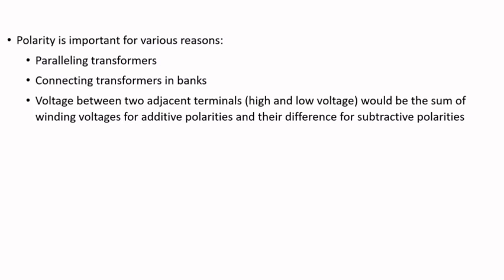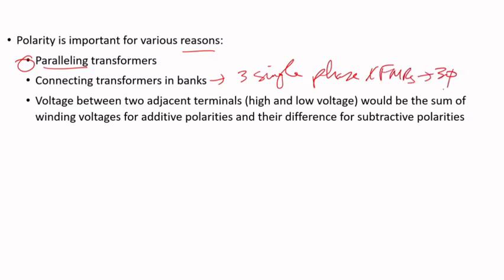So polarity is important for various reasons. One, if you are going to parallel transformers, you want to make sure they're connected the right way. Connecting transformers in banks, so you have three single-phase transformers, and you want to connect them as a three-phase bank. So you want to know which leads to connect to which to make up the Y, delta, and so on and so forth.